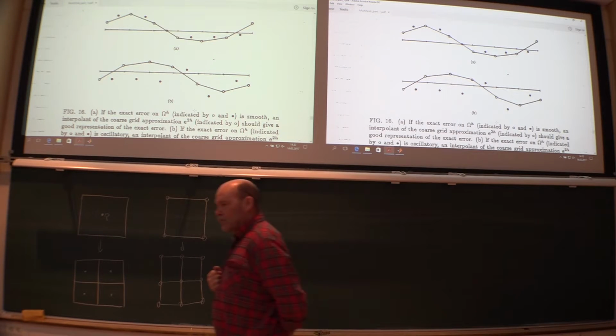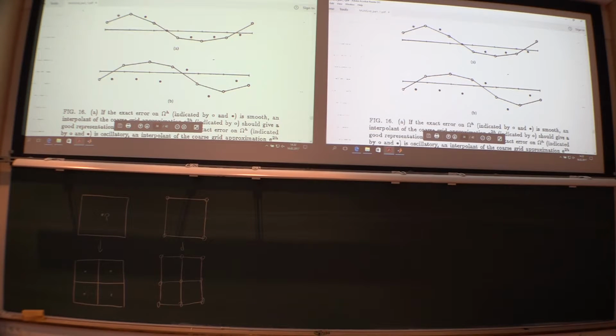And here is the danger. If you are going from a fine mesh to a coarse mesh, the signal that you have on the fine mesh must be smooth. You can't have any high frequent noise like the one in situation B here on the fine mesh. Here you are going from this guy straight up to him, down, up, down. No way you can give a good representation of that behavior on a coarse mesh. You have to smooth it out first. So here, this high frequent signal must be smoothed out before you can do this transfer to a coarse mesh.